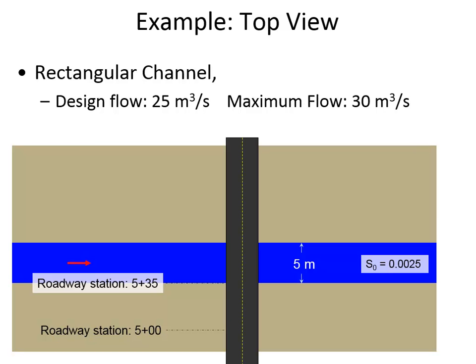There could be a different channel slope upstream of it, but it just basically looks at the water right at the front face of the culvert, and it doesn't do a lot of calculations upstream of the culvert. And so if the water level is getting deeper and deeper, you can assume that it's definitely choking the flow in the upstream direction, but it's only doing tailwater calculations, not headwater calculations. So it doesn't need the upstream slope. Maybe it'll be the same, maybe it won't. It doesn't have to be different.